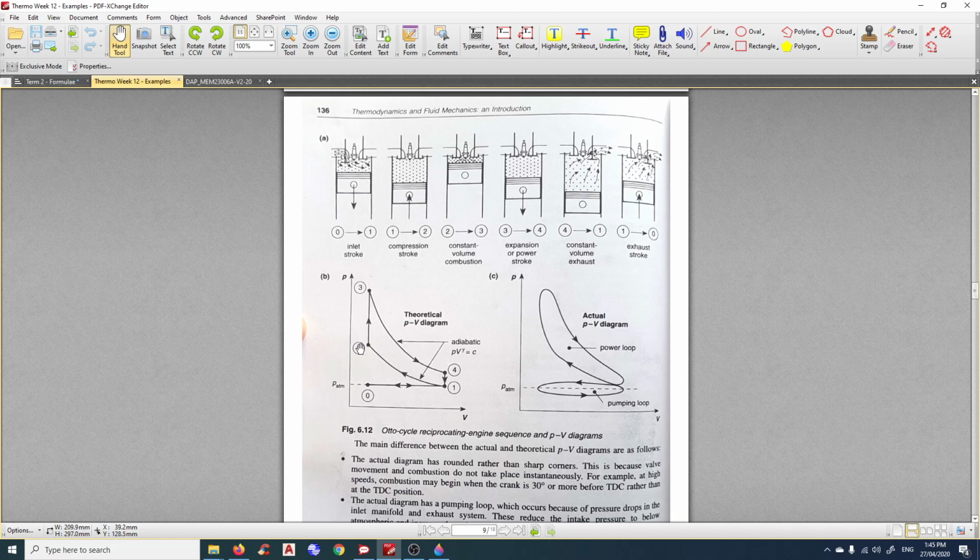So at that particular time, there will be no heat transfer. Of course, if you compress it 1,000 times, then there will be heat transfer. Hence, we have a heat sink or radiator to cool this cylinder. But we only look at one particular time frame here. So it's being compressed in an adiabatic process.